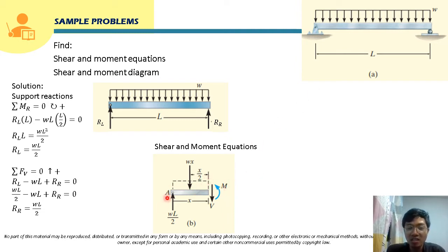As you can see here, this rectangular, uniformly distributed loading still has an intensity of W, even if we cut it here. So its equivalent point load for this rectangular loading at this segment has a height equal to the intensity W and a base equal to X. Solving for its point load will just be solving for its area.